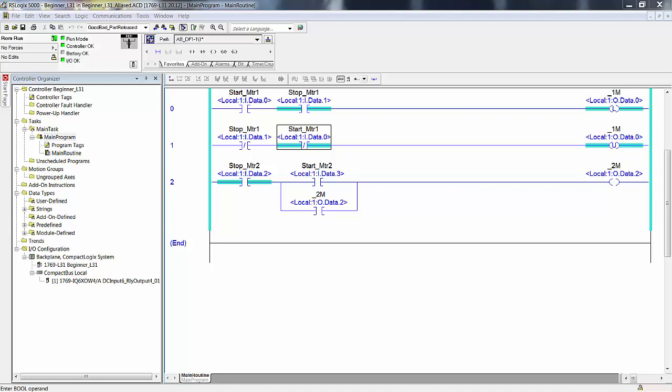We will not integrate the photoelectric eyes until much later in the manual. Depending upon whether or not you have switches wired to an input module card, and how many switches are wired to the input module or card, you may have to use program tags defined as booleans, but not aliased to an actual member of a module-defined data type, meaning you may have to have start push buttons that are tag names, but they aren't aliased to an actual input because you don't have any inputs or you don't have enough.